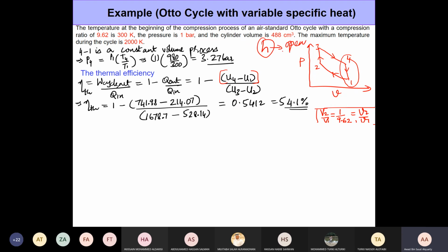Now there is a special case where we also look at enthalpy differences, which is what happens when you're looking at the work done in a constant pressure heating process, but that is just an exception. But whenever you're looking at closed systems, the internal energy change is what you're looking at. That's because in an open system, we also have to deal with flow work, which appears as PV. So you have U plus PV, which is why we look at enthalpies.